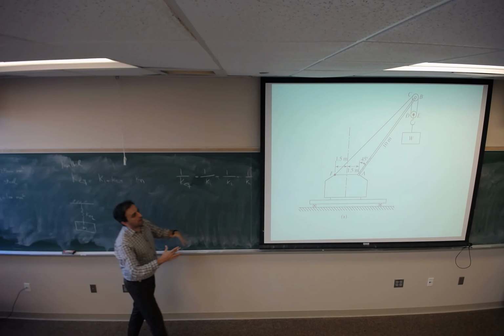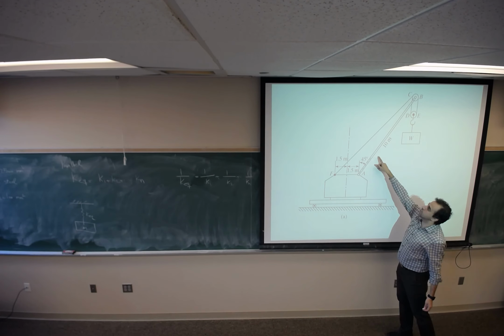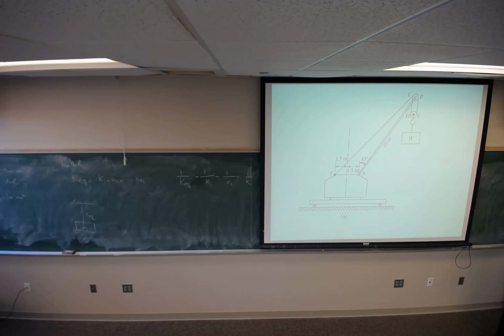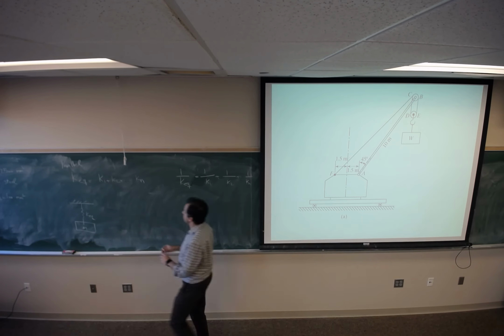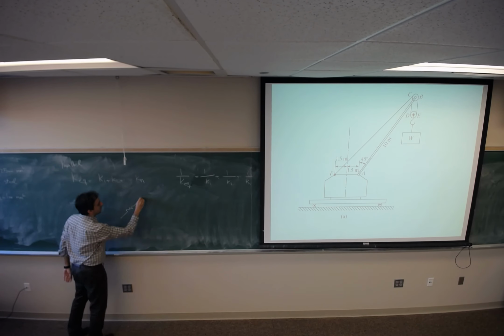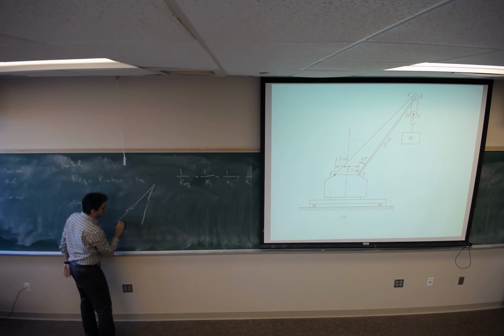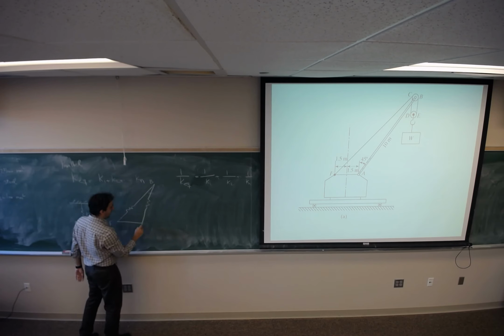But it's going to be difficult if we consider mass for AB. Since the mass of AB compared to the weight that you have here is small, you can neglect the mass of AB and FC and say they are massless, and we model them as two springs. We just consider the stiffness of cable BF and boom AB.